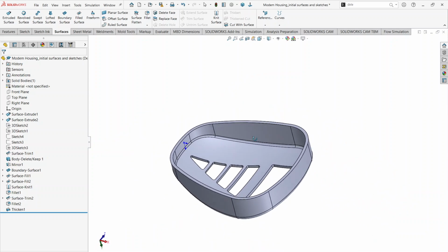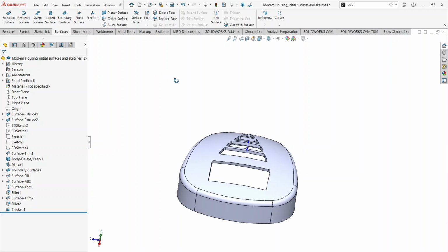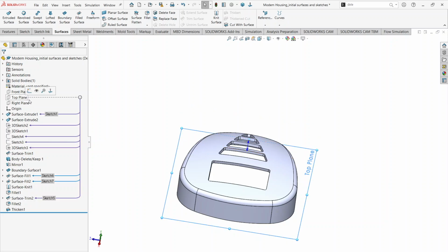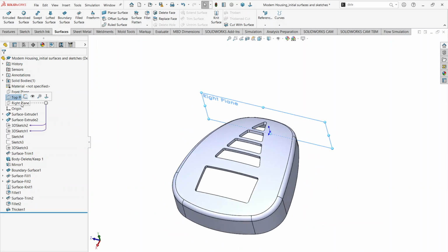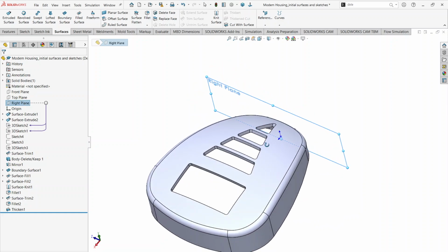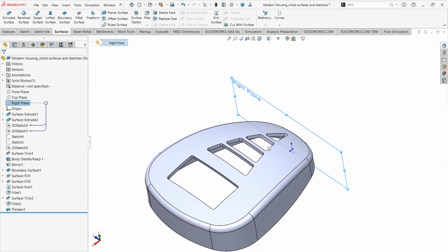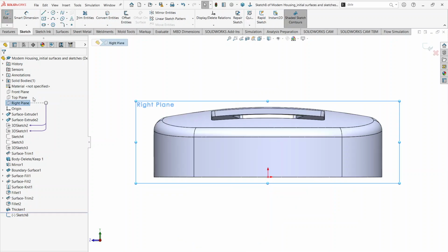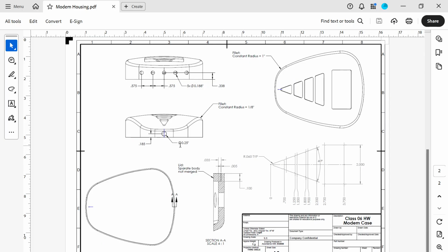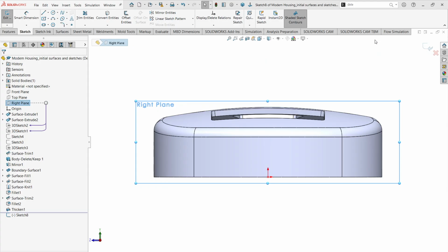Okay. So I do have two cutouts to create, which I'm going to go to not top plane, maybe right plane is the one that I need to select, but the cutouts should be in different modes. So I would select the right plane for the separate type of cutout. So first, the easiest cutout is one hole in the back, which is 1/4 of an inch with 0.185 from here, from the center.